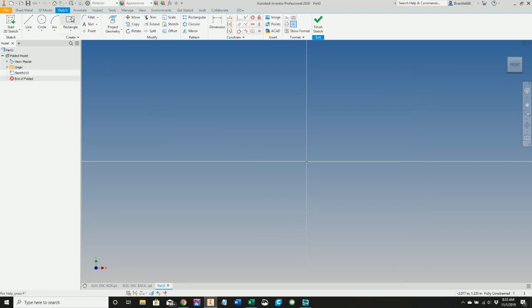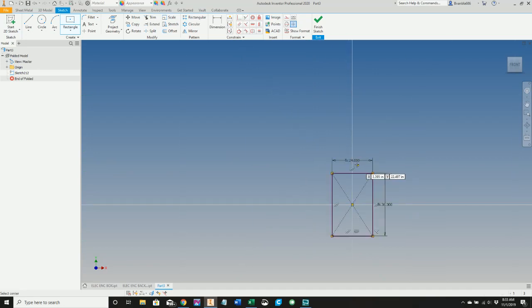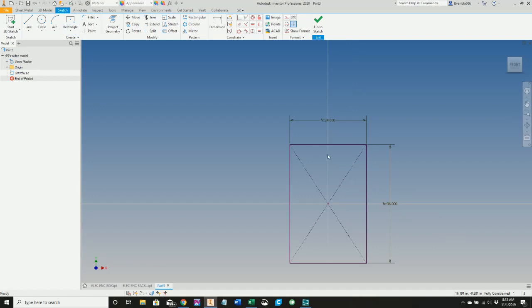We are in the sketch tab. I'm going to go 2-point center rectangle based off of the origin as always, and we're going to put in enclosure width, and you can see how it turned from red to black, saying that it's accepting that. I'm going to hit tab, and I'm going to put in ENC length. It turns to black. It's accepting it. Hit tab again, and we are good. So now we hit enter, and now everything's black. So black is happy. It's fully constrained. It can't be moved anywhere.